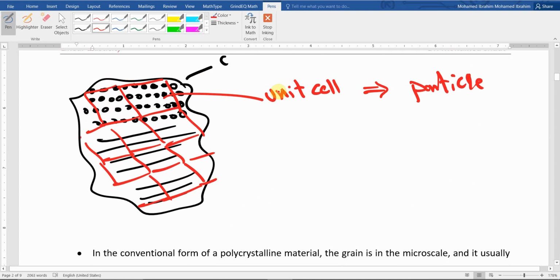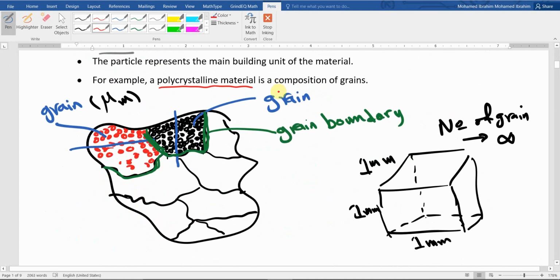For example, if we go back again to the polycrystalline material example, and look at the atomic structure of the grain, we said that the atoms inside the grain have a certain crystallographic orientation, a well-defined atomic arrangement. The next grain has another crystallographic orientation. It is not another arrangement of atoms, it is the same arrangement, but oriented at a different angle, right? We have one direction and a different direction, opposite, perpendicular, or any other angle.